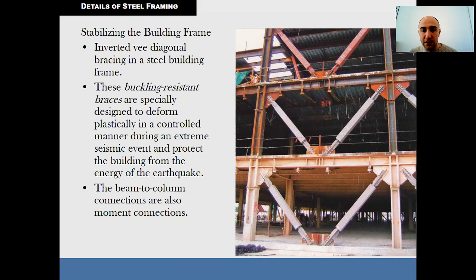Buckling restrained braced frames have significant advantages over other vertical braced frames. The most important thing is that it allows the steel core to resist the full axial forces developed in the bracing, as designed. The casing, through its flexural rigidity, provides lateral support against the flexural buckling of the core.